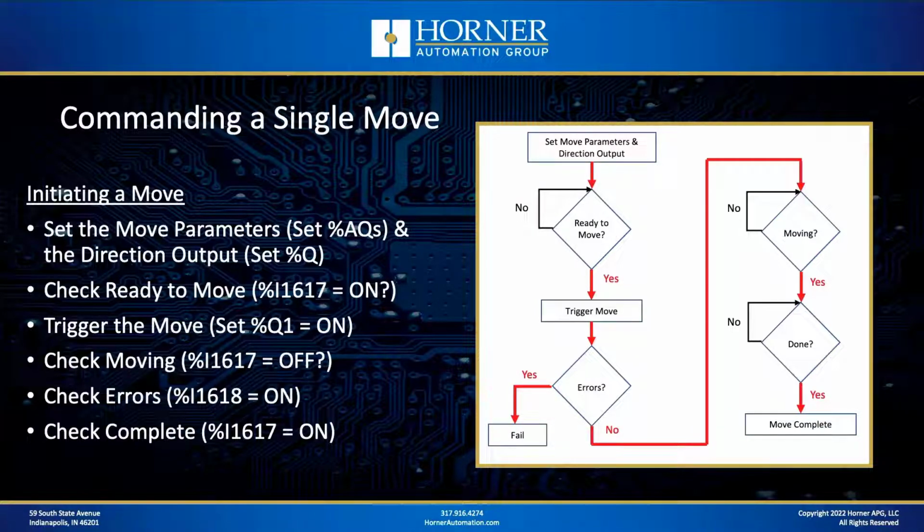There's two steppers potentially built into the OCS, stepper number 1 and stepper number 2. The pulse output, or the step output, is available on Q1 and Q2 for those two stepper functions. Now, what about direction, you say? Well, you'll want to use a general purpose output, one of the other solid state outputs, to tell the motor which direction to turn, or tell the drive which direction to turn.